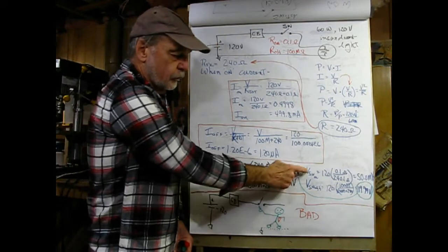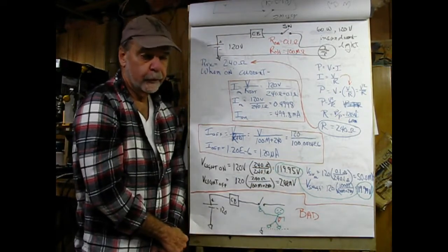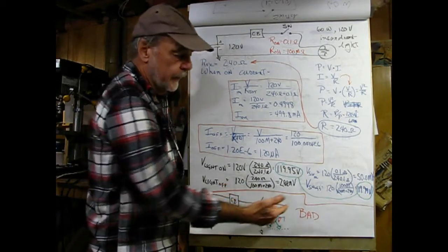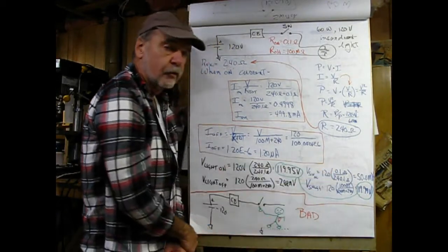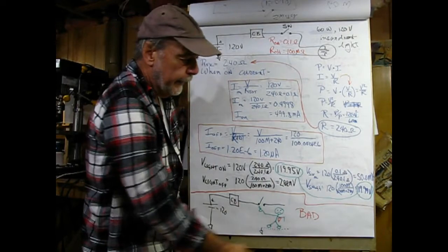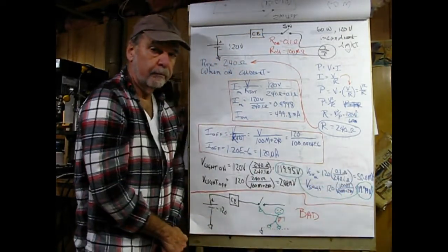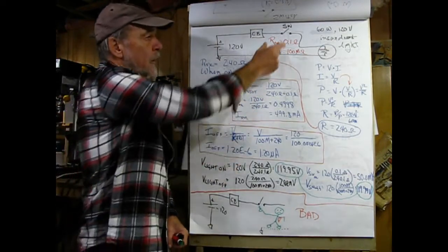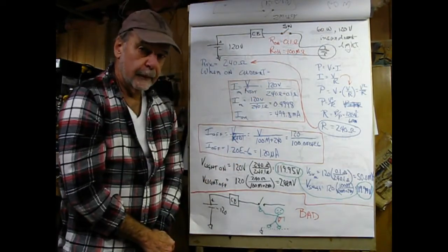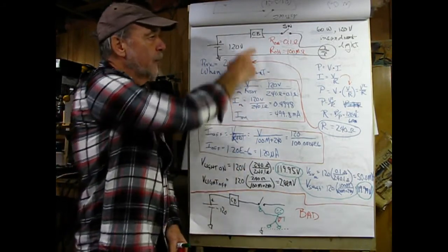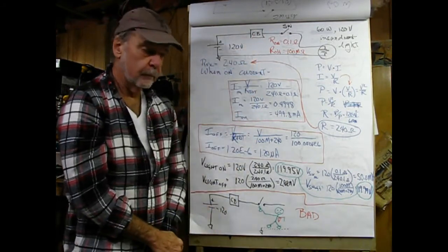Now, what's the voltage drop across the switch? Well, as you can probably guess, it's going to be pretty low. So we'll use a voltage divider again, except in the numerator we have 0.1 ohms, and that comes out to be 50 millivolts. So if we were to take a voltmeter and go across the switch when the circuit's on, we would measure about 50 millivolts. Oh, and CB here stands for circuit breaker.